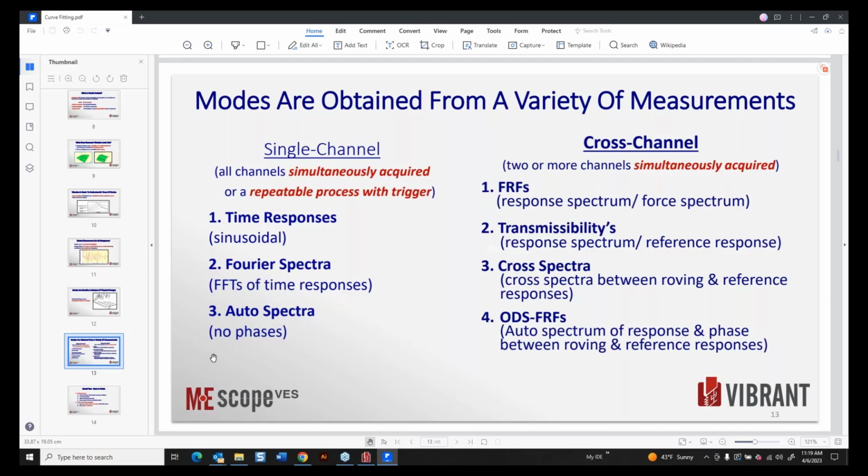And just capturing that data with analog gear is a good approximation of a mode shape. And that's the way it was done in the bad old days. But in the 60s, with the creation of the fast Fourier transform, the FFT, and then in the early 70s, the onset of digital spectrum analyzers that use the Fourier transform, they're now very common tools for engineering and vibration analysis.